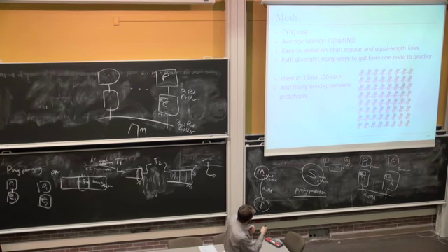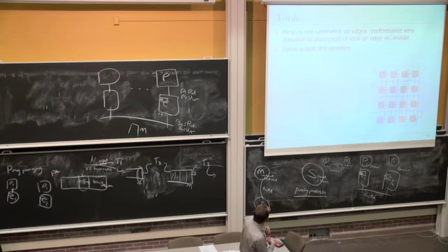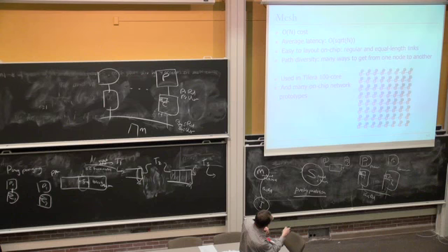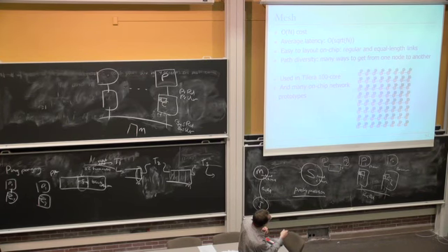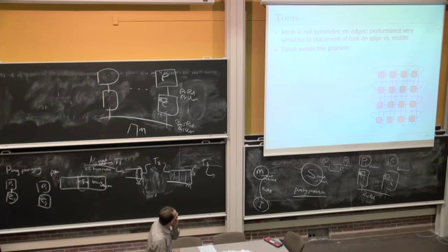Okay, so one problem with mesh is if you want to communicate between this core and this core, you need to go through all of these routers, right? It's not symmetric, at least on the edges. Which means that if you place something here, then you need to traverse all the way here, these 7 routers in this case, to get here. But if you added this other link here, that communication would have been much faster. Right? And that's the idea of a torus. That's basically that other link that I showed you here.